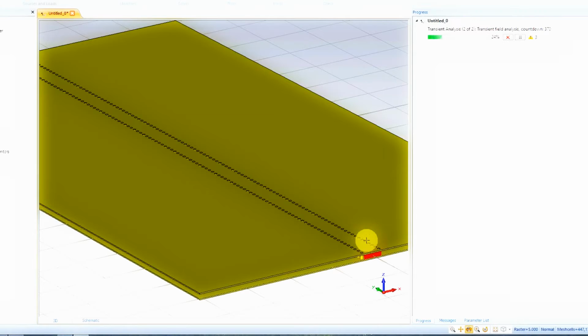If you simulate over cutoff, the stuff just bounces back and forward, and it never reaches that. Well, it does eventually reach that minus 30 dBs, but then your results are wildly wrong. Frequency domain solver uses a phasor-based technique, but it has to do many frequency samples. So particularly if you're doing wideband applications and non-resonant kind of stuff, it does take longer, and it is better to use the transient solver.